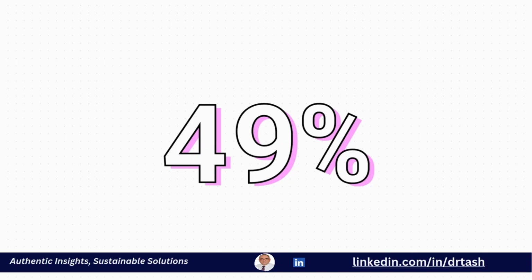Now do the math. 0.8 cubed is about 0.512. That means you're now using just over half the original power. That is a 49% cut in energy for a modest 20% reduction in speed. It is absolutely incredible when you see it in practice.